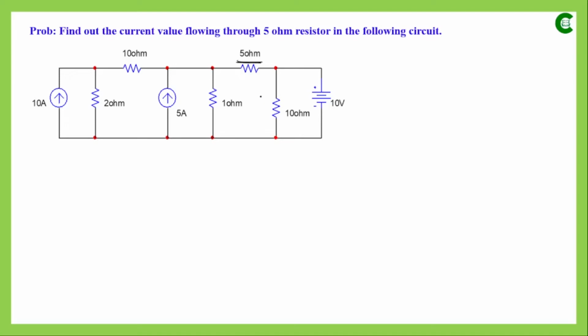the first thing that will come to our mind is that we will apply KVL or mesh analysis. Second, if we see that most of the components in that circuit are connected in series, and we can also identify the different loops in that circuit, then also we will try to apply KVL or mesh analysis. But in a circuit where we have mixed sources, like a few voltage sources and a few current sources, it becomes a bit confusing which law to apply, Kirchhoff's voltage law, or Kirchhoff's current law, which we will learn next.